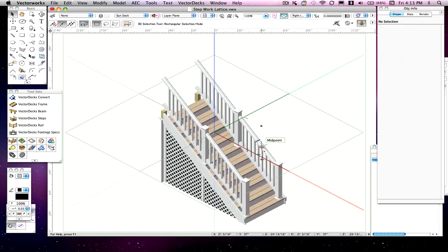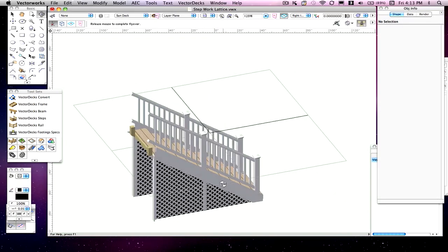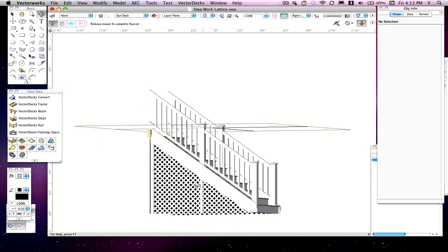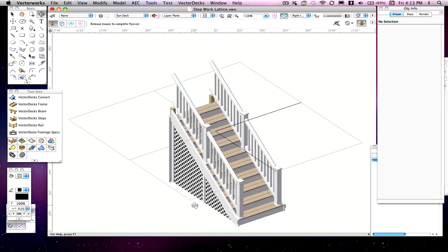And click OK. Now the step is now drawn with the lattice, and it's trimmed out on these corners, has that L-shaped trim, so if this was pushed up or butt up against any lattice that's on the Sundeck, then it would cover that inside corner. Now let me rotate this around just to show you how it draws it completely around it. It trims it out. It butts up against the bottom of the trim of your step.